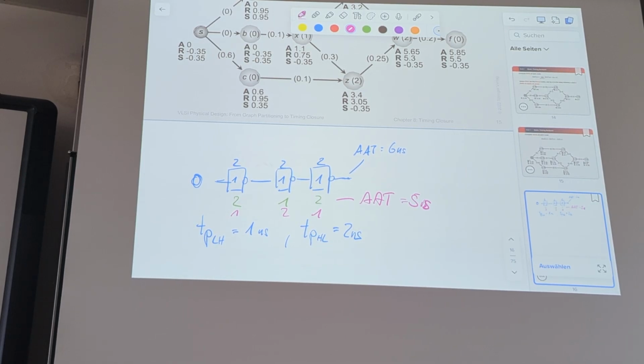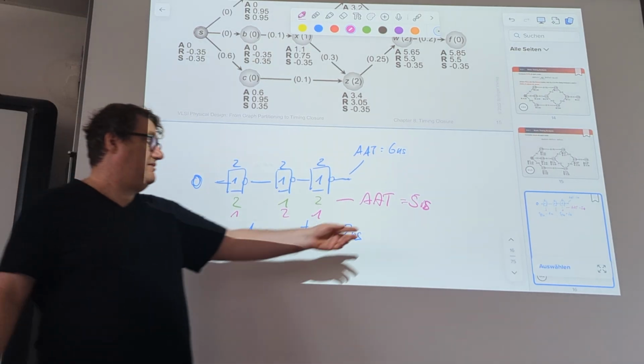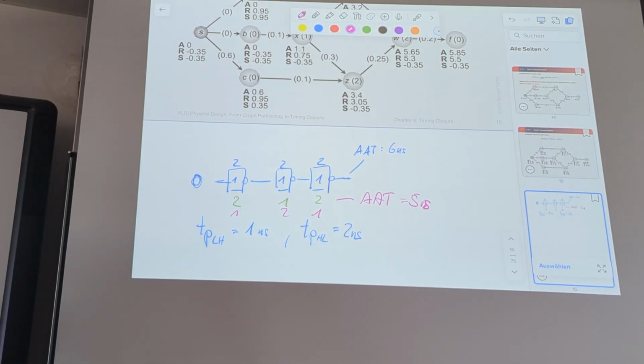And this shows that by changing the algorithm, adapting it and making it smarter, you can make a timing verification which tells you that you can run faster. You have not changed anything in the circuitry. You only made a smarter algorithm which tells you that you have 1 nanosecond more time, meaning you can increase the clock period by that amount without doing anything. So that's an example.